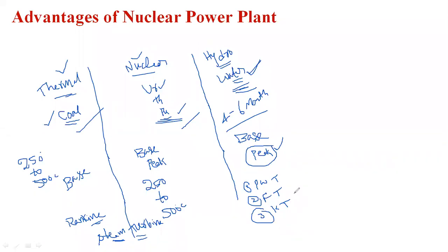Based upon the available head, they are generating the power, and the turbine is also classified into three types: the Pelton wheel turbine, the Francis turbine, and then the Kaplan turbine. In the Pelton wheel turbine, the shaft position is horizontal. The Francis and Kaplan turbines are the medium and low speed turbines, and the shaft position is either horizontal or vertical.